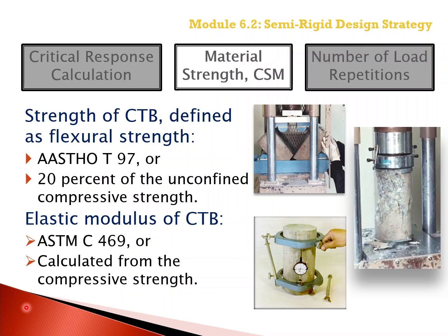So remember the different input variables for the chemically stabilized layer as a review from Module 4-4-3. The 28-day compressive strength, or the modulus of rupture, is measured in accordance with AASHTO T97. And then the 28-day elastic modulus is measured in accordance with ASTM C469.